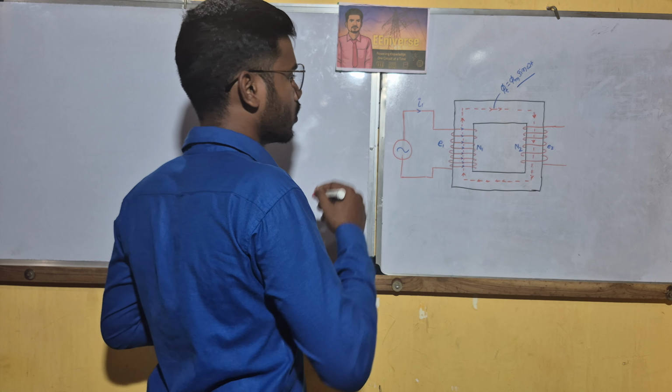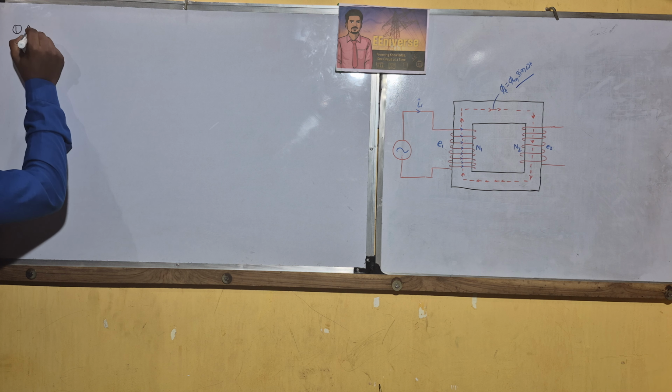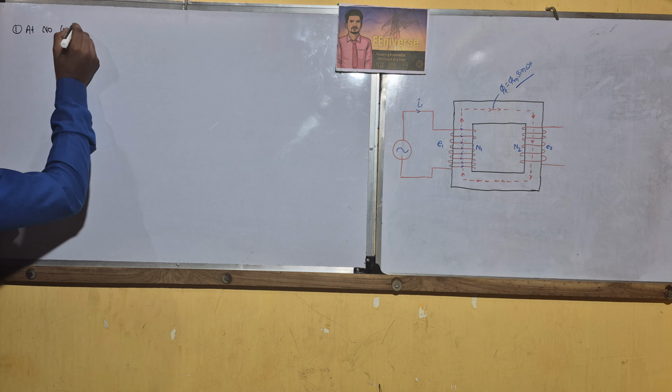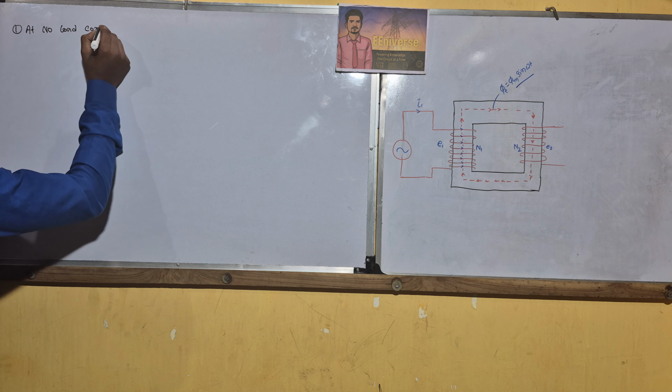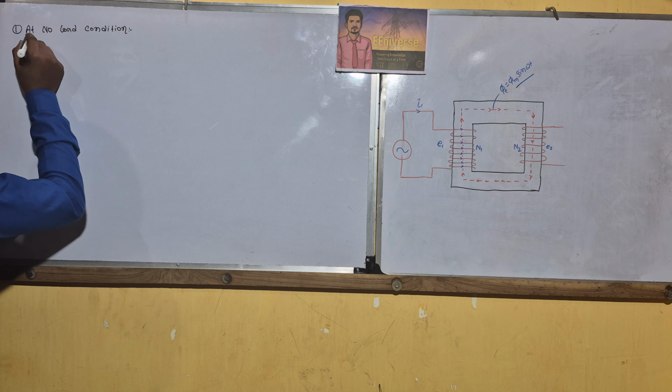So now we can write, at no load condition, the main flux, that is phi t, equals phi m sin omega t.